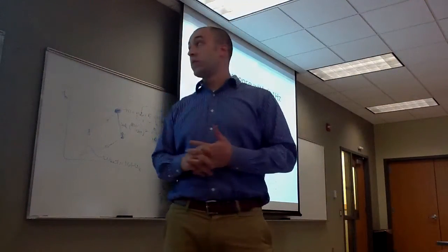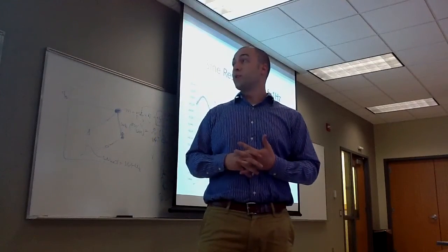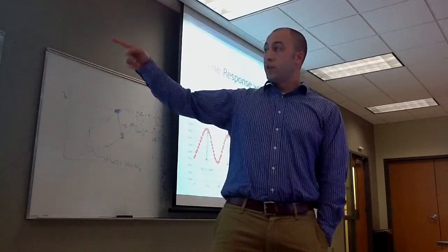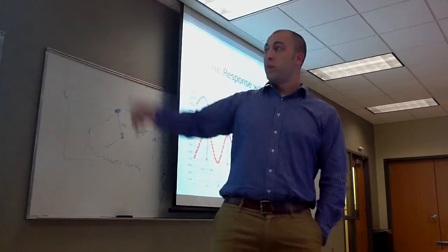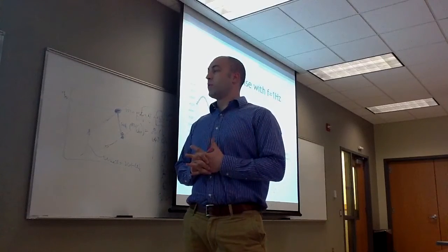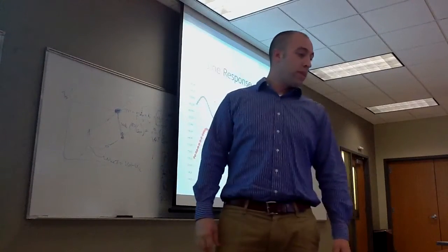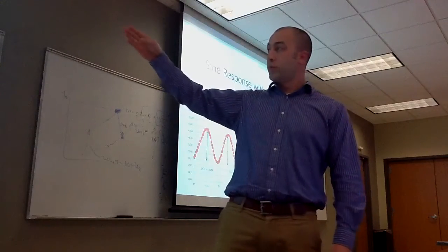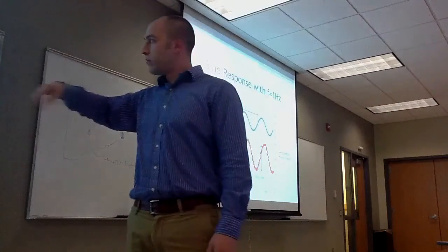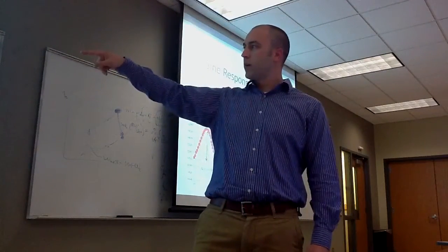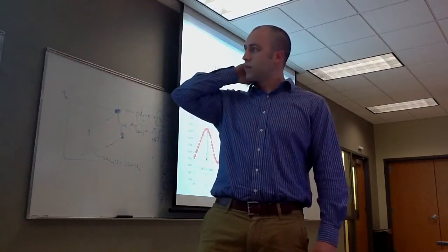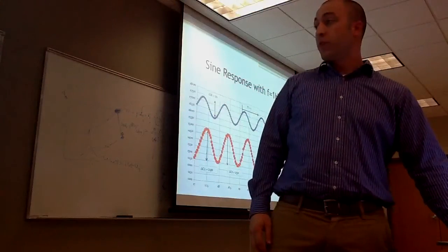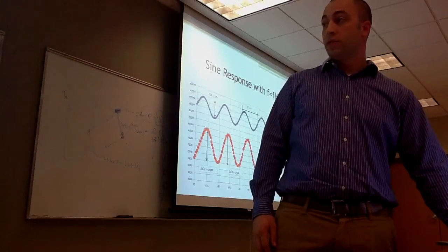Here's an example of one of our sine responses with the frequency of 1 hertz. We are able to find the change in input, which is the M, was 20. We measure that from the top of the peak to the valley right after it. Then T equals 1. You measure that from the peak on the output to the peak on input, I think. No, I forget. Then we found the 3 different change in outputs to be able to find the rest of the information we needed.